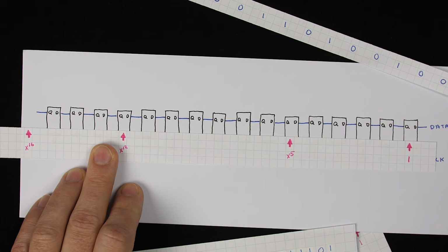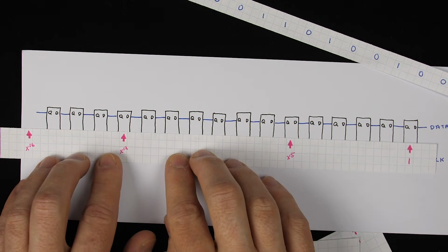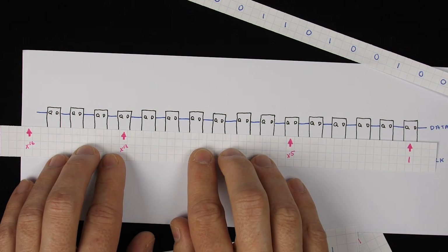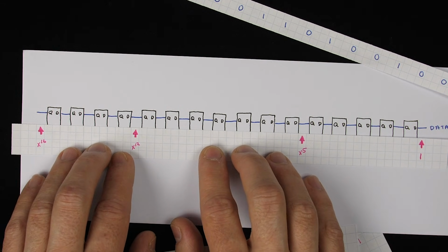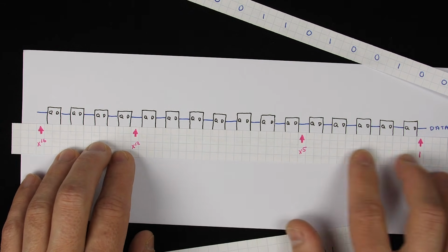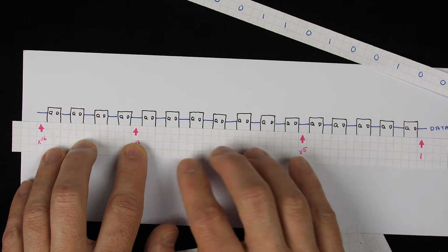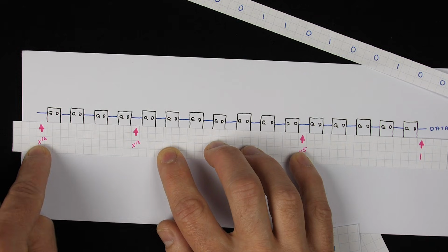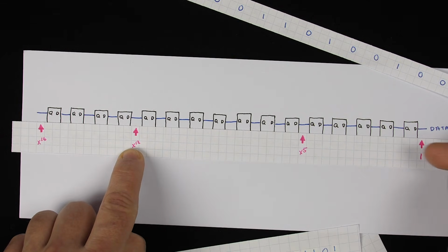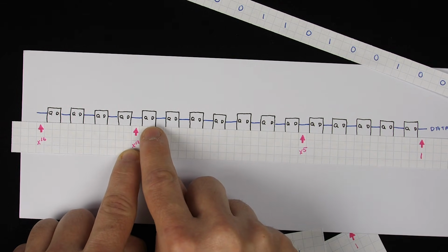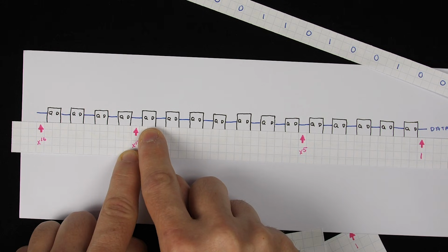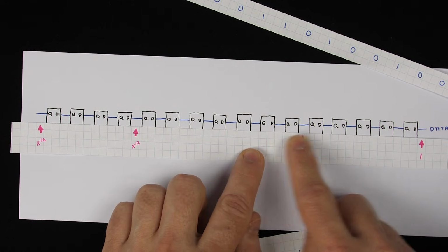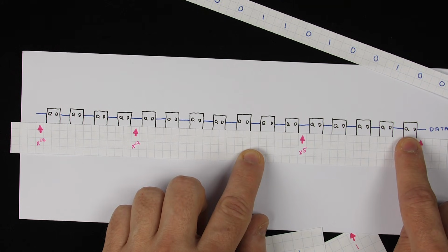And then the other trick here is rather than thinking about how do we flip what's in the register, what we can do is think about flipping the data as it enters the register. So if we just slide this over a little bit, this maybe changes the way we can think about this. So we can say if what's coming out of this last register is a 1, then when we do that shift, we want to flip the bit as it shifts from one register to the next. Or here we want to flip the bit as we read it into the first register.